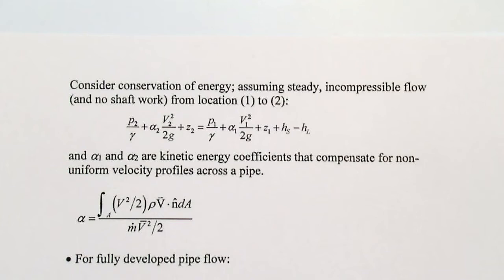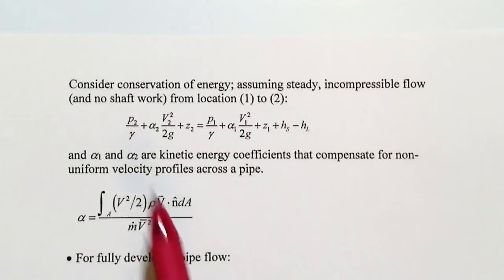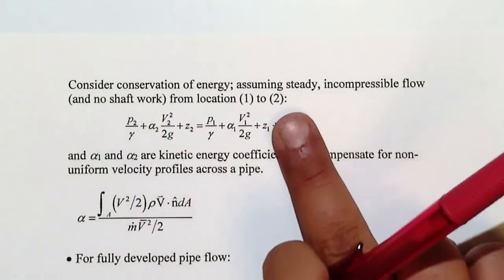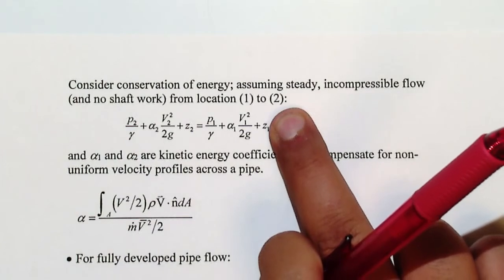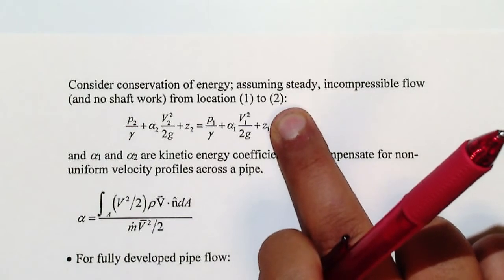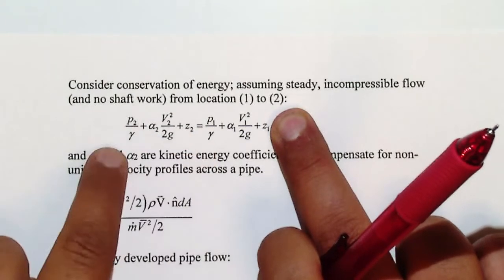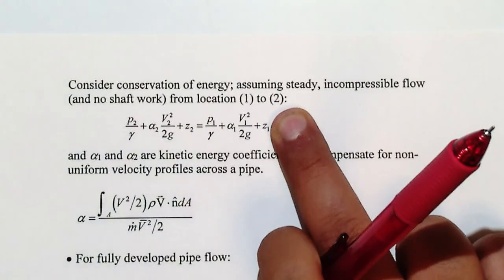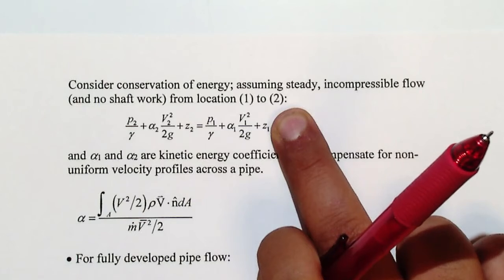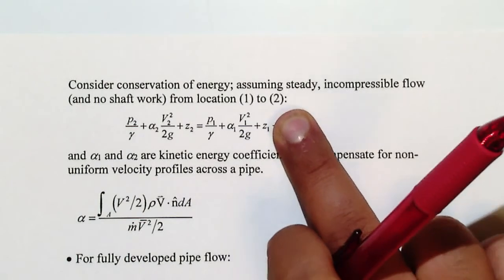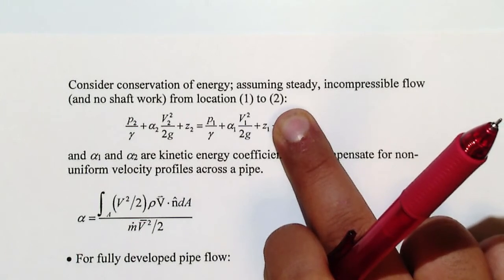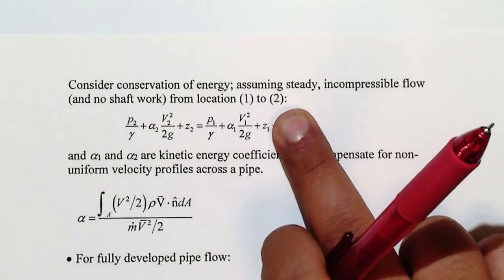So if you have a streamline inside the pipe and apply Bernoulli, you will find that by Bernoulli these two are zero. Okay, so at first you assume that there is no loss in the pipe. You will find that you need a pressure difference between these two. So P2 and P1 should be different. Why? Because we want the flow to move inside the pipe. So flow moves from higher pressure to lower pressure, right?